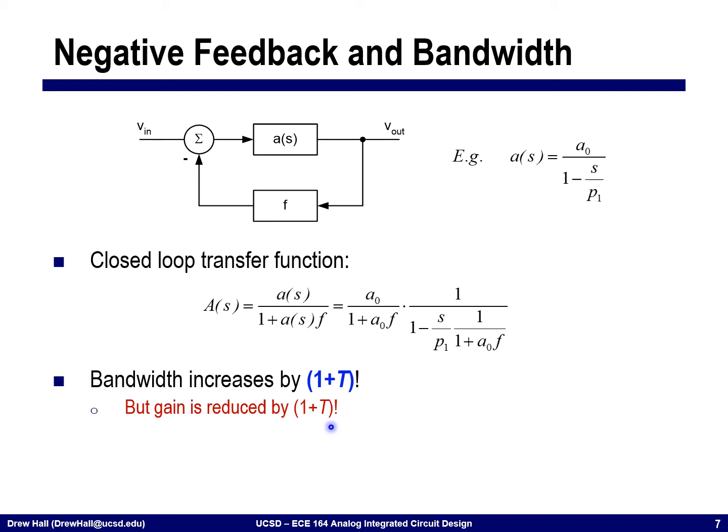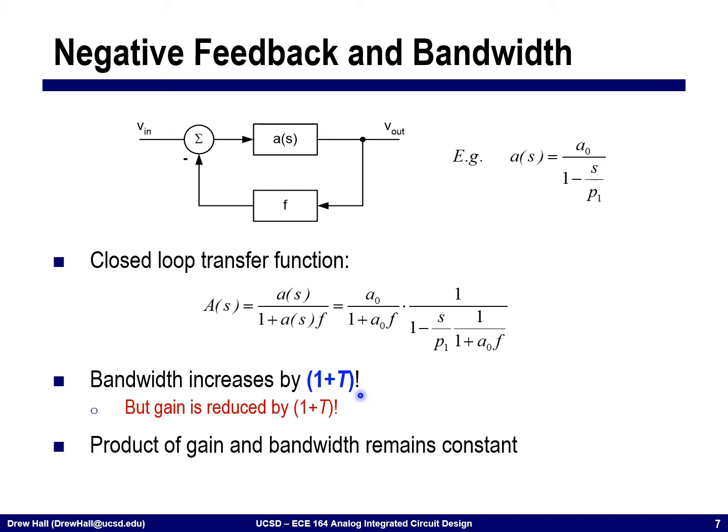And so if you've ever heard anybody say that the gain bandwidth product is constant, this is essentially the trade-off that we're talking about in this particular system. If I have a particular architecture for a forward path amplifier, I can change the feedback network, but essentially the gain times the bandwidth will always be constant regardless of how I manipulate this feedback network, provided that it's passive.